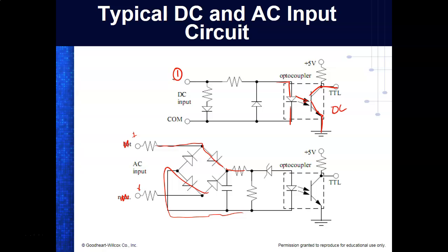But what I want you to know is that whatever we put over there, the internal works of the PLC is isolated from the load by these optical couplers, which are pretty neat. And they're little tiny things. They're usually 4 pins, 2 for the input, 2 for the output. Very small things. And these have been used in PLCs since they first came out.